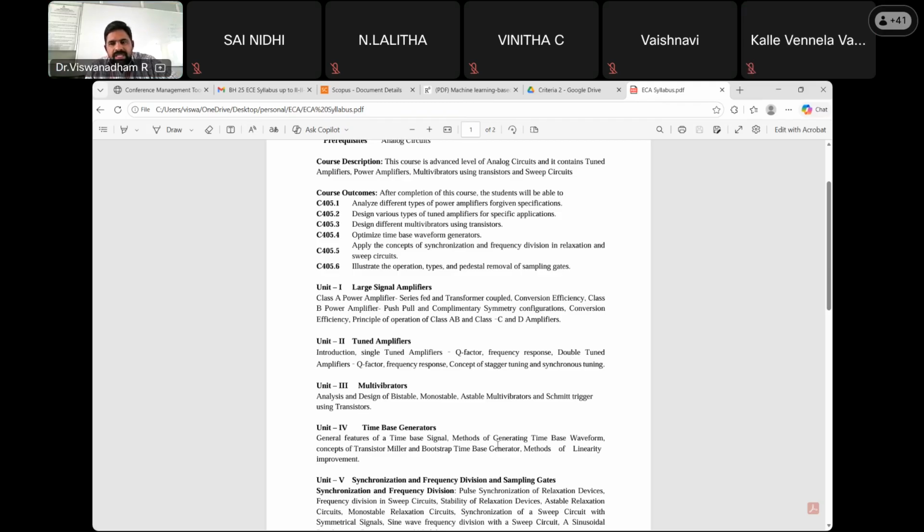Okay. So then just ask any queries with respect to unit 3, please. And here one more thing with respect to the Schmitt trigger: if the question asks about the Schmitt trigger, you need to mention hysteresis. What is meant by hysteresis? UTP minus LTP. Okay, hysteresis. You need to know what the hysteresis loop means and all.